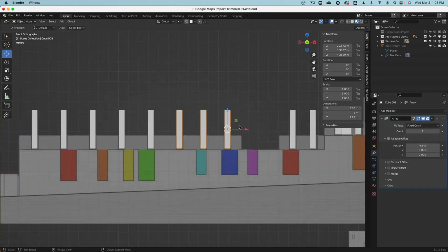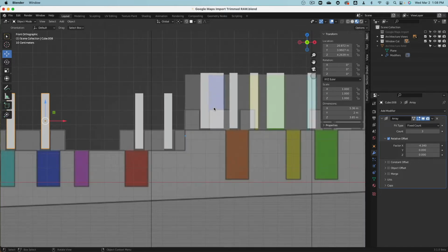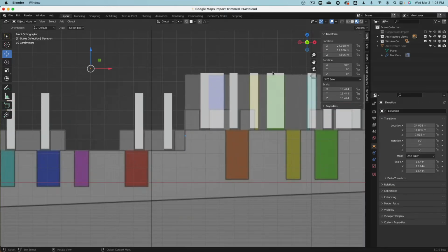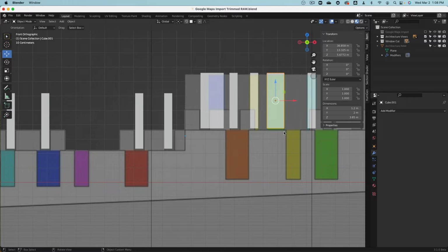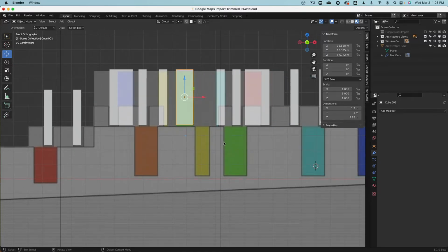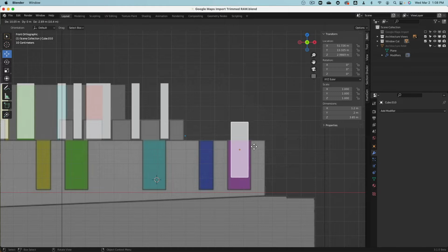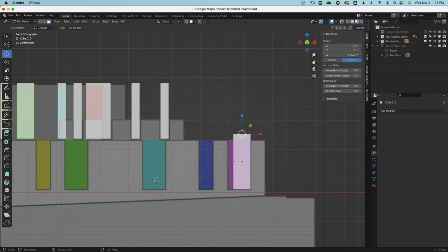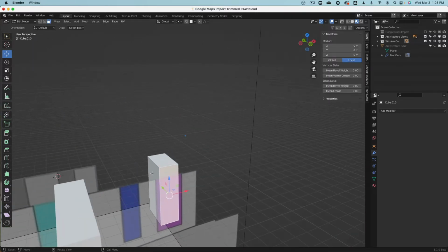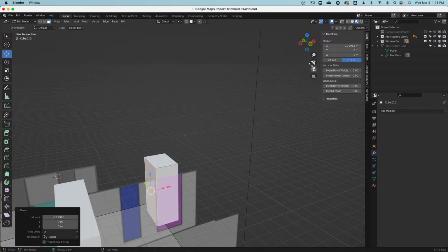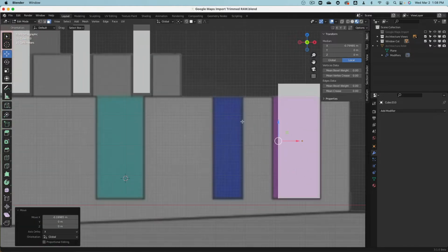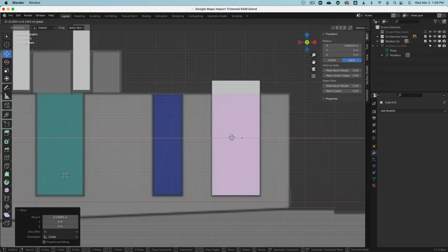Okay, beautiful. And this window here is definitely different. And is this different? I don't know. So I select this bigger window here. Shift D, yeah, because this is bigger. I move this to there and then go into edit mode, face select, click on this face, and then I drag this over. See how I'm lining this up? Beautiful.